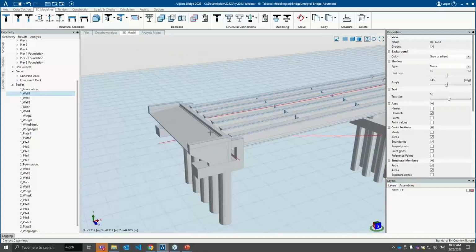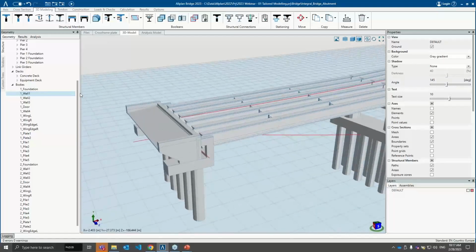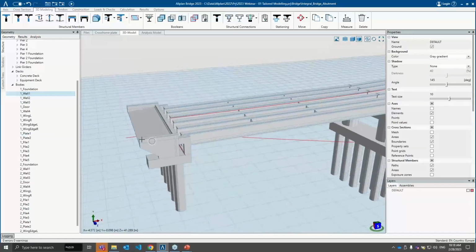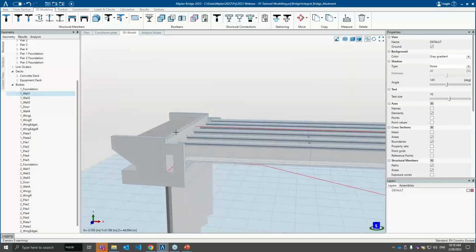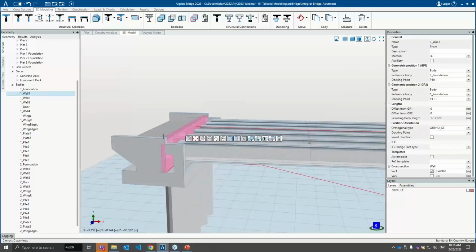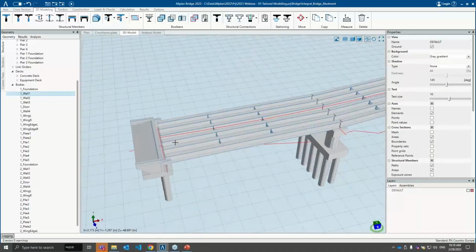The advantage here is that elements that you create with free parametric modeling can be reused later by partially exporting them and importing them back into the project. Also, you can introduce any kind of change to the parent object. Maybe if it's this wall that we have, and you change the height, the thickness, or the position, everything will also move. So basically we have an overall integration.